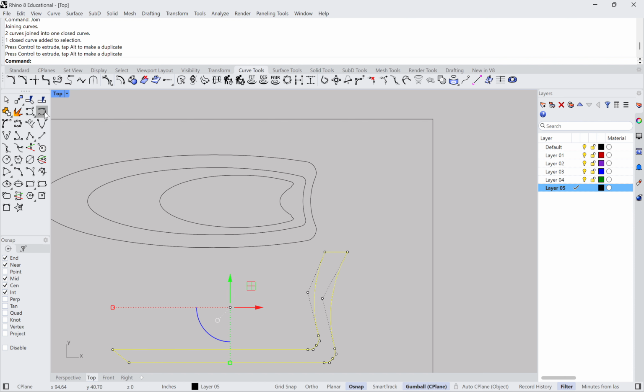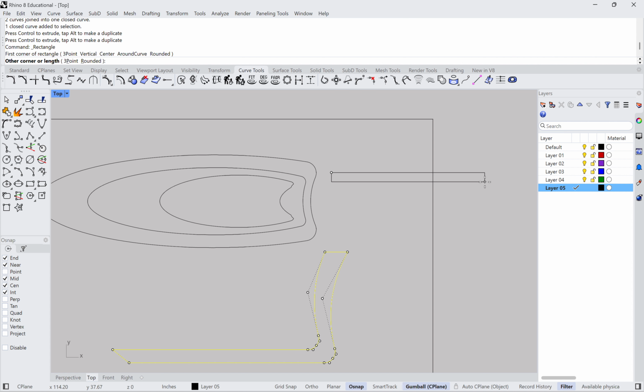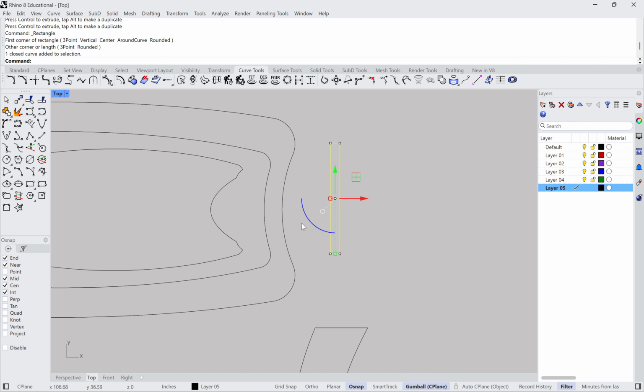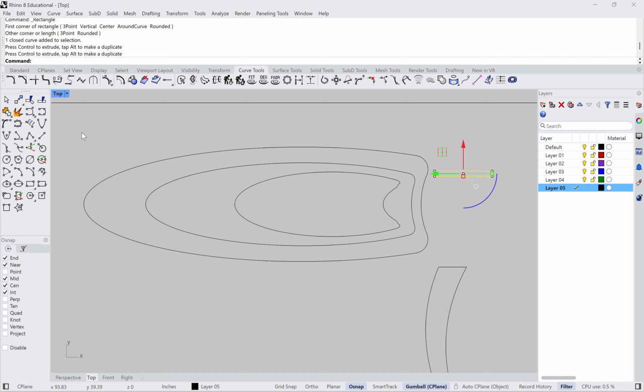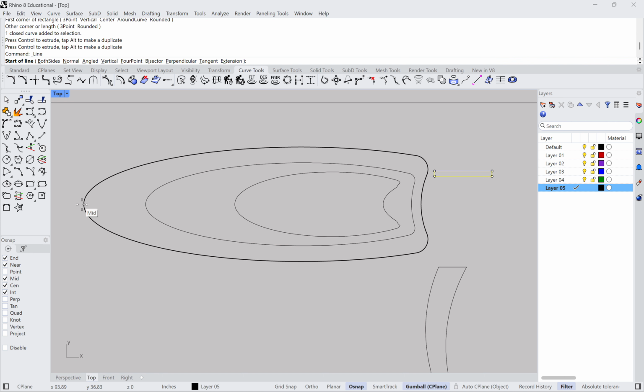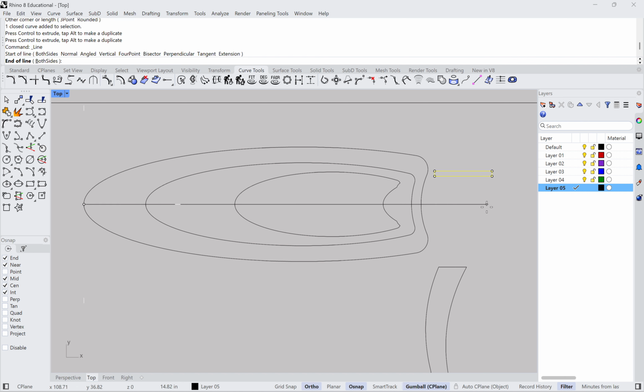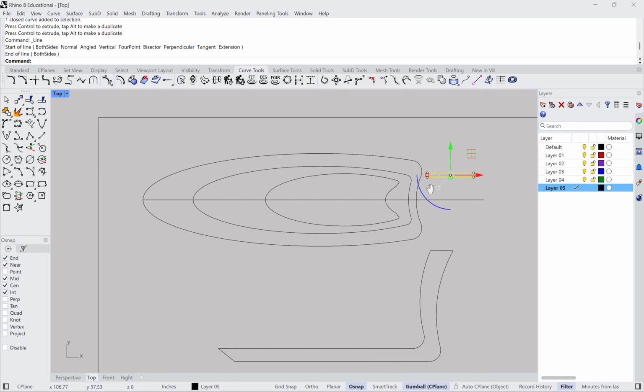Before I make a copy of this, I need some of those rectangles. So let's see, 0.1875, right? That was our 3/16 of an inch. So here's a 0.1875 rectangle. And I want to do this symmetrically. So I'm going to use a single line as construction geometry, start it from the midpoint at the front, and then bring it all the way back here like this.